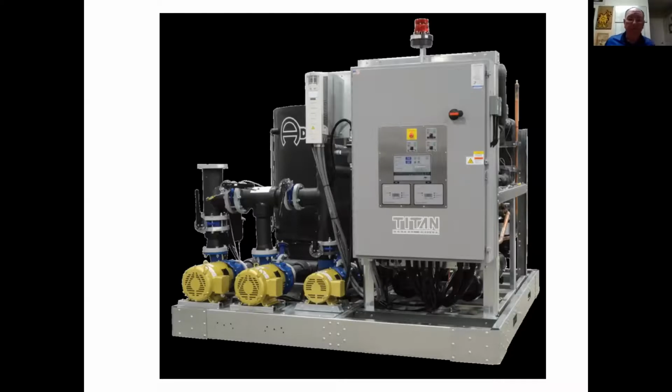So if it's at 50 and your set point's at 50 degrees, then odds are it's hit that point where it's doing its job, and you only need to run one circuit, and maybe that circuit needs to run at a 50% capacity. But if that temperature goes up, that means you've added more load to the process. The controller is going to say, okay, I need to turn the second zone on in order to cool that water down to maintain 50 degrees.